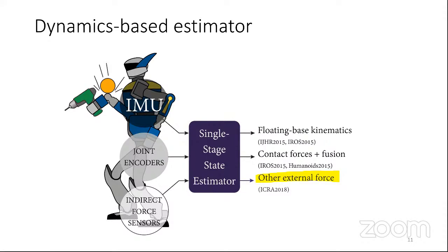The force component was not really good, because with the IMUs you cannot get all the components of the external force. You can get moments that can deform the robot. So you mostly get 3 DOFs out of the 6 DOFs of the forces. So it is possible, but the quality is much lower.